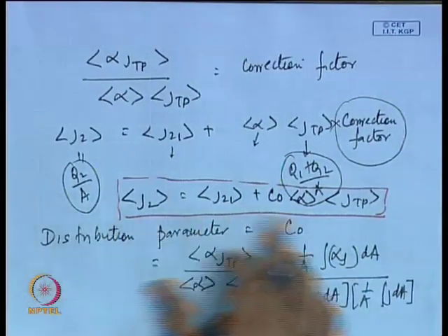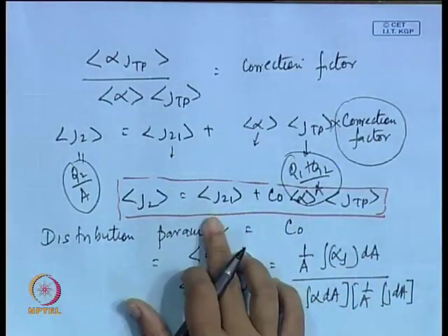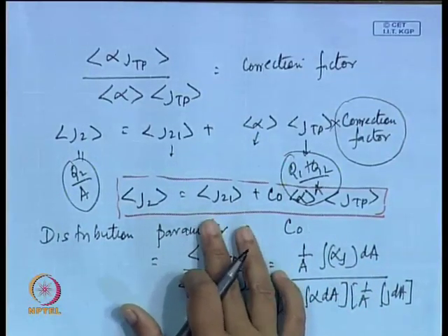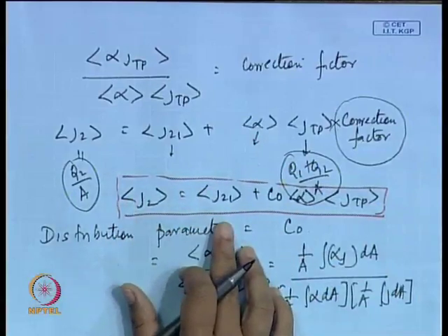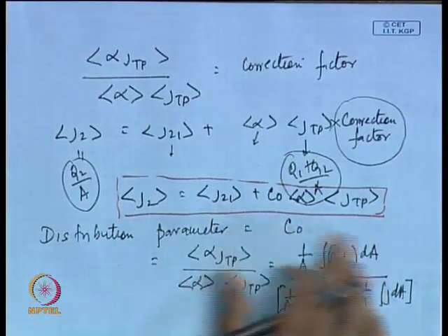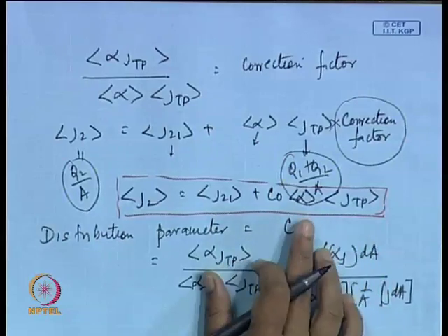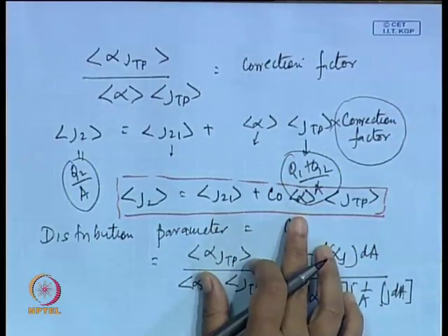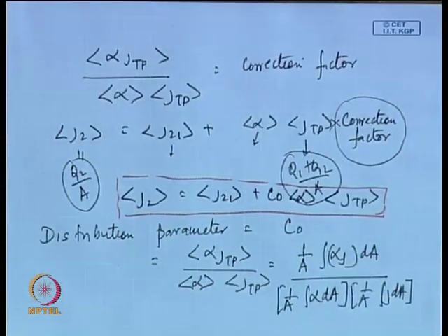Okay. So, in this term we find that if we can find out C0 and if we can find out J21, then this equation can be used for finding out alpha, for all practical purposes. Once we can find out alpha from this equation, this alpha can be substituted in the rho TP, U2, U1, kinetic energy terms, momentum flux terms, etc., and all the terms can be deduced accordingly. When these terms are substituted in the pressure drop expression that we obtained from the homogeneous flow model, we can get a much more accurate estimation of pressure drop as well, correct.